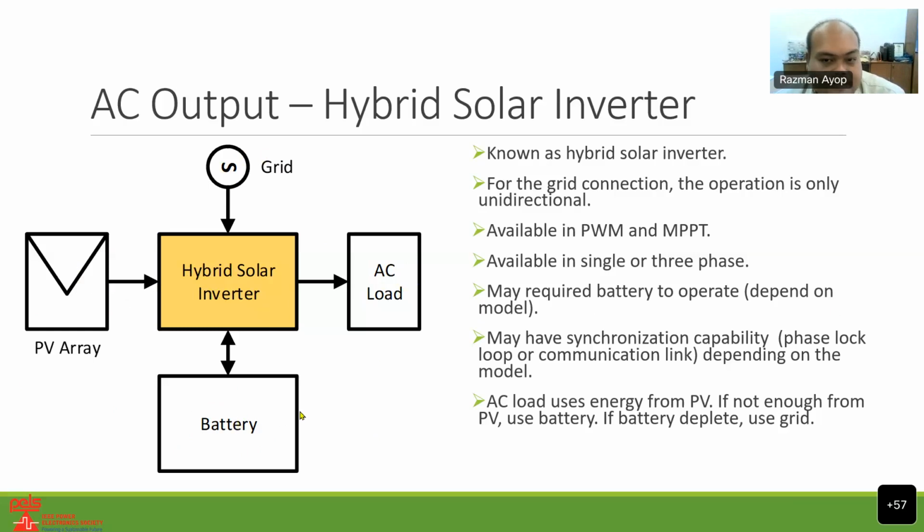But in another case, if we don't have a battery and the grid is offline, and my load is lower than the PV, is it possible? Cannot, because PV is not stable. That can be a problem because, for example, PV produces 100 and the AC load is 200. Where do they get the other 100? So it needs to have a backup, either grid or battery.